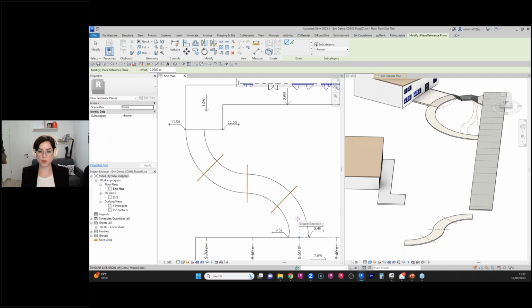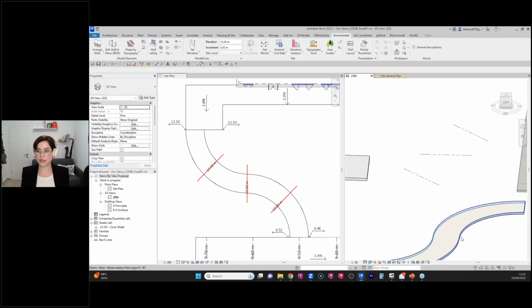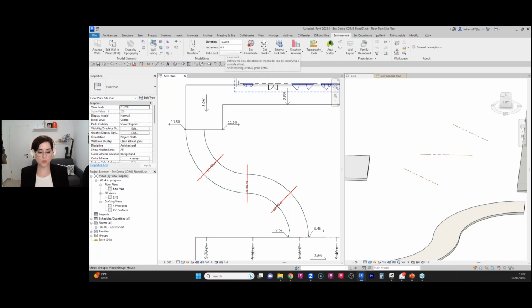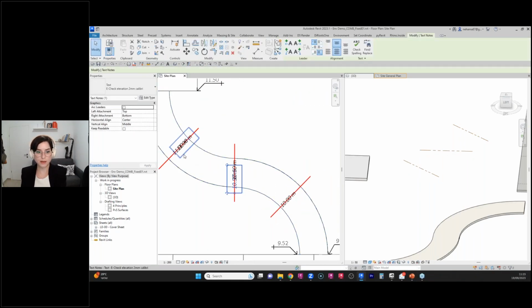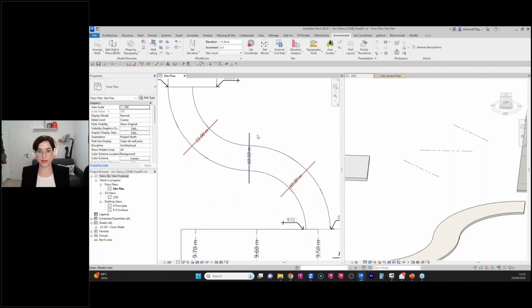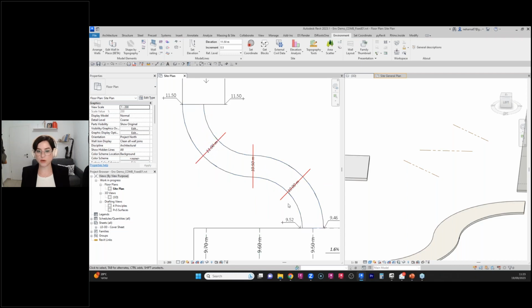Now take a look at my 3D view as well. I'm going to click one time here, one time here, and then two things happened. The lines changed elevation. They changed their color to indicate that the elevation is different. Oh, sorry, I didn't insert a value of the increment. So the vertical distance between the lines, I want it to be 50 centimeters. That's what I forgot to do before. Doesn't matter, I'm going to do it again. 1, 2. I got double the text. That's not an issue. All right, so now I have 10, 10.50, 11, and 11.50. So I know that my elevations are in place.